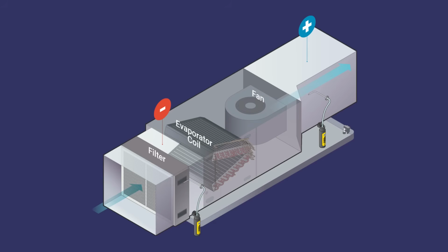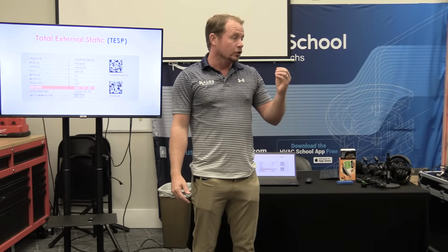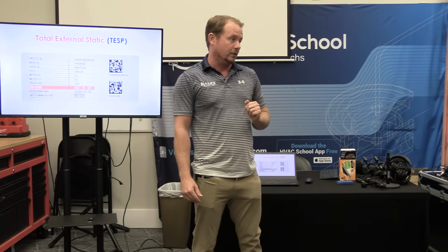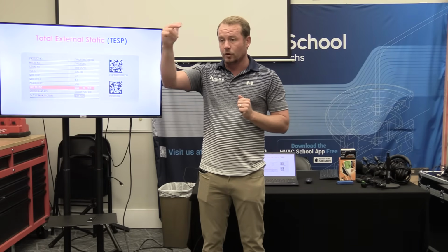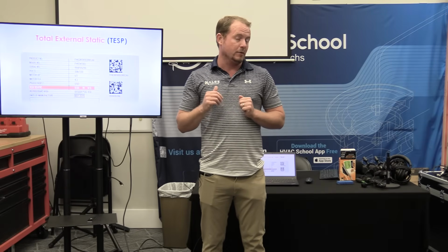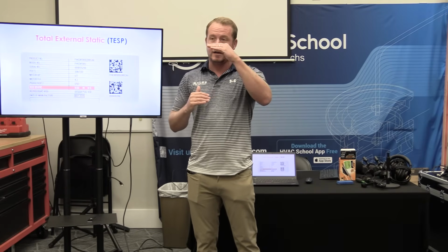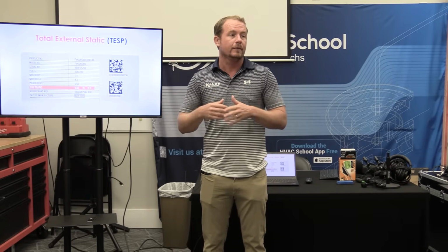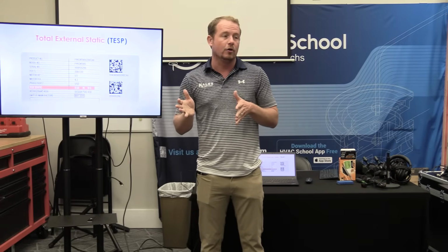On an air handler, what doesn't that count? Evaporator coil, right? That evaporator coil gets dirty, that blower is increasing in the amount of static pressure that it's seeing, but we're not measuring there, right? We're not measuring our static pressure right above and below the blower. But can we? The answer is yes, we absolutely can. And we can look at what our pressure drop is across our evaporator coil quite easily. All we do is one probe below, one probe above, right? You measure that differential in pressure from top to bottom of that evaporator coil, and that's going to tell you what that pressure drop is. Now, we would have to know what it's rated for in order to know whether that's good or bad.